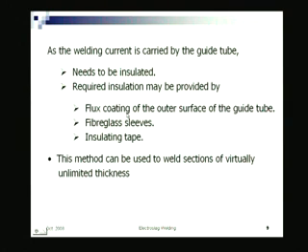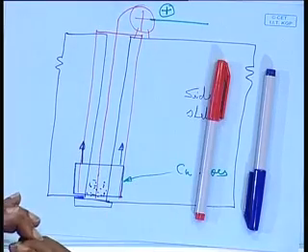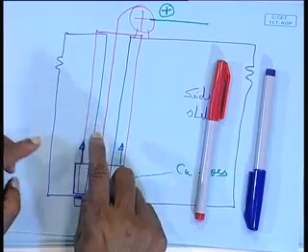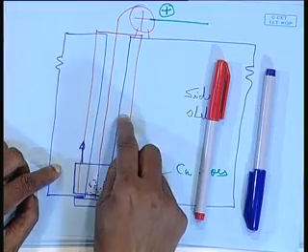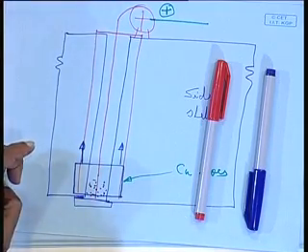This is a complicated business, because that consumable guide means what? The guide which is supporting the feeder electrode, right. And the guide tube also is providing a support, but it also gets melted and deposited, right. So, that means that is also a metal. And it is guiding through this, that means that guide tube again should not touch this. So, you will have to properly insulate to ensure that even if it touches, nothing happens.